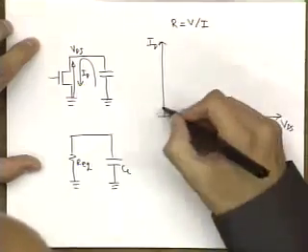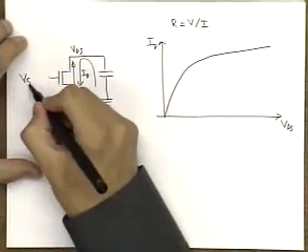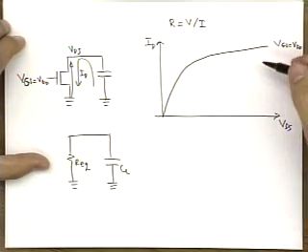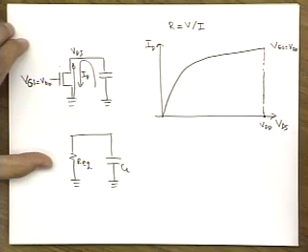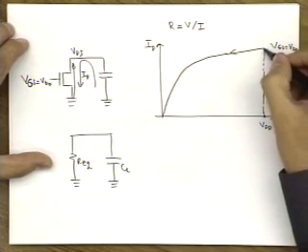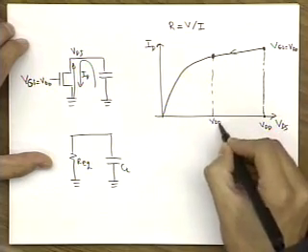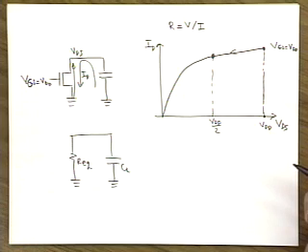And then when you plot a curve ID versus VDS, assuming that VGS is equal to VDD, for example, what you have is that you're starting your transition over here at VDS equal to VDD, and what you're interested to find is how long it takes to traverse this path, starting from the operating point at VDS equal to VDD, going all the way down this curve to VDD over 2, because that's where you define your delay as the time it takes to get to the switching threshold.